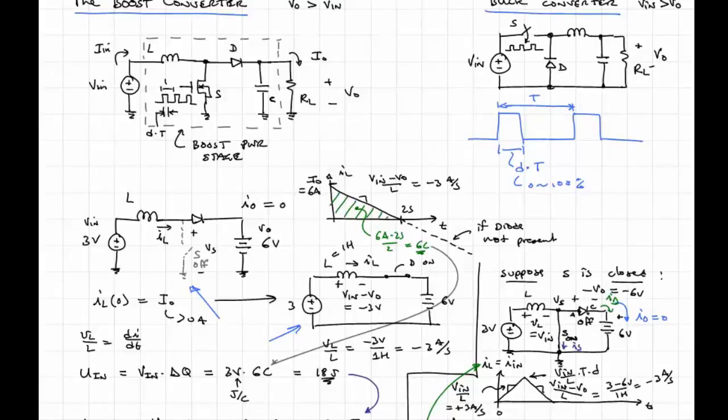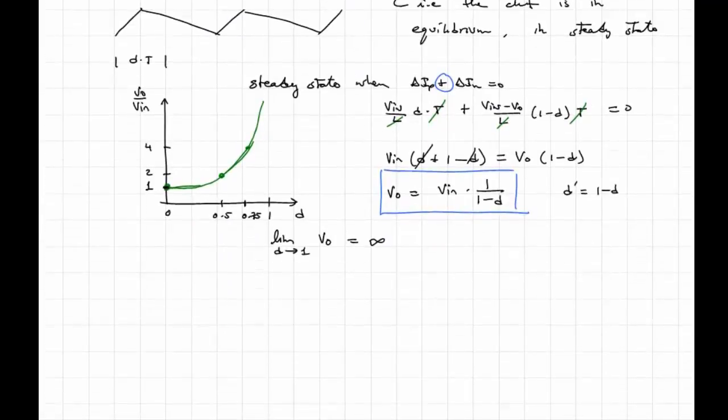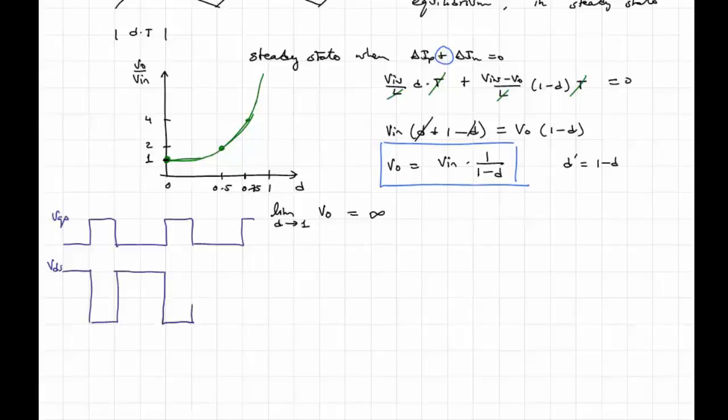And so let me go back here. Just to recap then, if we apply a driving signal, a PWM signal, to a MOSFET, so this would be VGS, we would find that the voltage VDS across our switch would look something like this, where it would go approximately up to V out, and it would go down to approximately 0 volts.